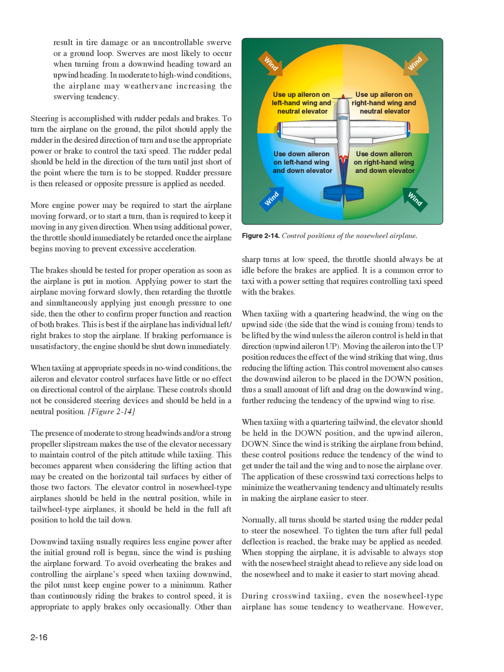To tighten the turn after full pedal deflection is reached, the brake may be applied as needed. When stopping the airplane, it is advisable to always stop with the nosewheel straight ahead to relieve any side load on the nosewheel and to make it easier to start moving ahead.